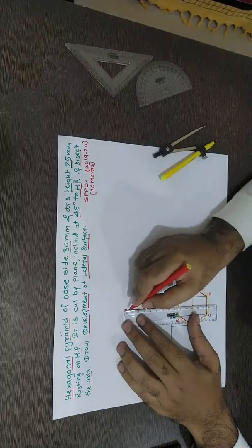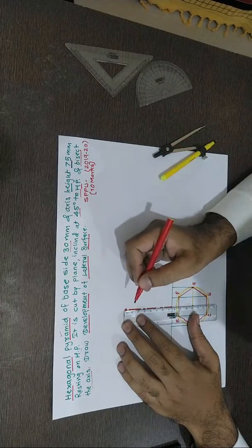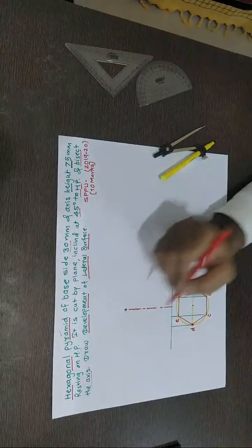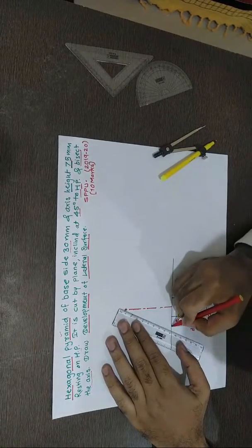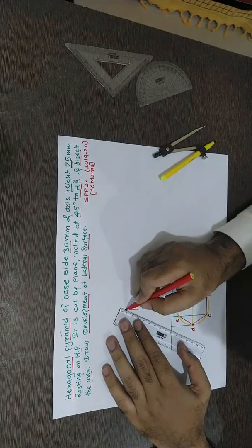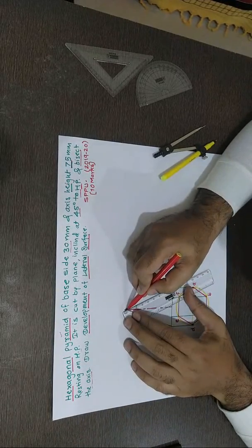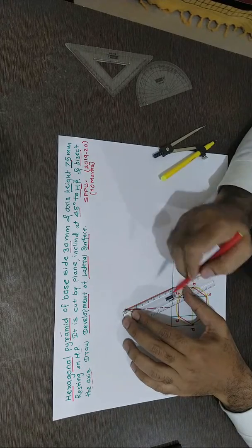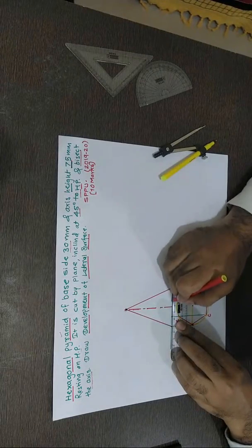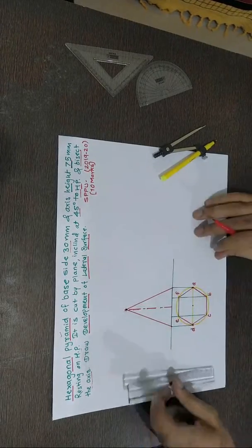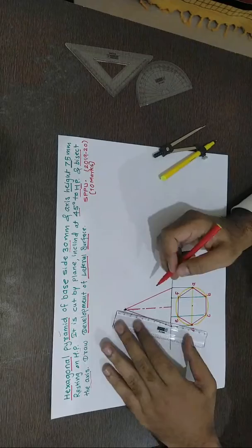And directly align the scale. You can take 75 mm in the compass and you can mark an arc here. No issues. Will be safe. So this is axis height 75. Join it. So this is just to join these ends. And this is of course a base also. Now we should join this edge also, CE and BF, from this point to this apex.